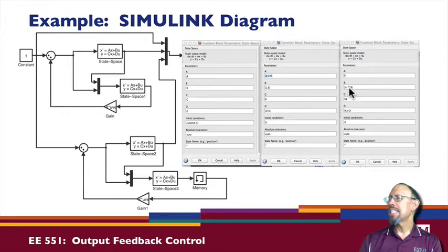Here we use LR and TB as the B matrix, KZ as the output for this system, and then we have KY. Remember, we have two inputs coming in, so KZ gets multiplied times Y, 0 times the U. So these are the state models that we use to simulate the system.